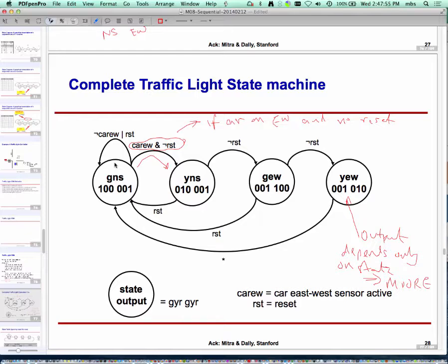Does that mean you could just take out that self edge then? You can take out that self edge, but for purposes of this course, if you decide to do it, then I would like you to put a notation that you are doing that, so that you're conscious about it, because otherwise it's also a source of mistake. Generally speaking, for purposes of this course, I would like you to draw all the edges, including the self edge, even though it results in a more cluttered state machine. That's normally the case with most tools also, but some tools do provide the capability to skip the self edge.